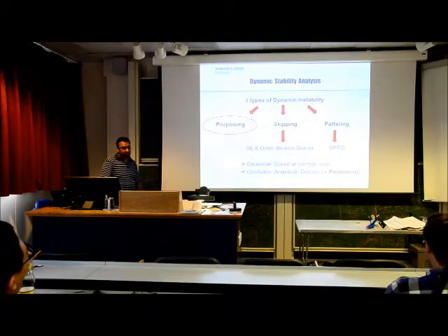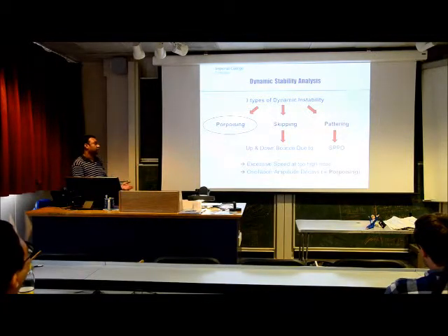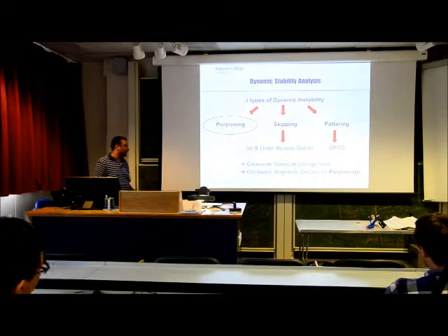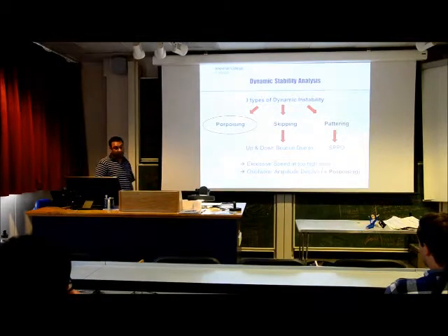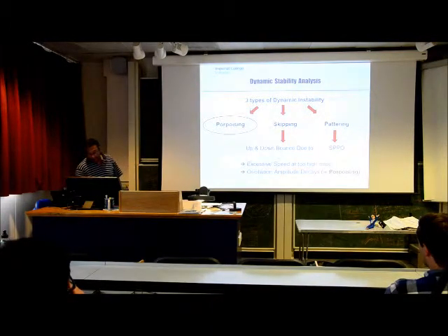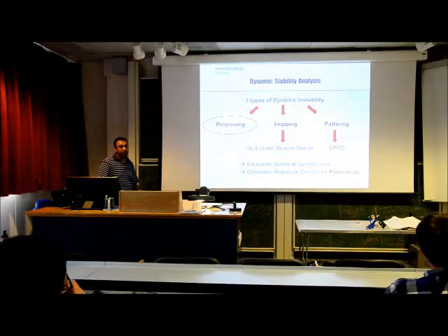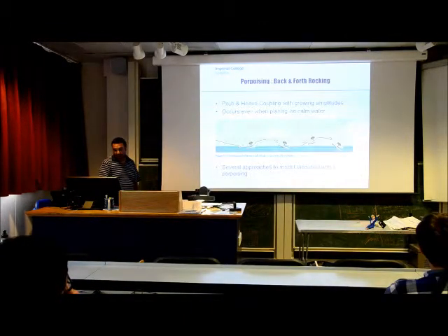But that's much less of a worry because generally skipping leads to a decaying oscillation, contrary to porpoising, which keeps on amplifying if no damping is done, but we'll come back to that later on. And battering is just an SPPO. So we care more about porpoising, which seems to be the industry's main concern about stability issues.